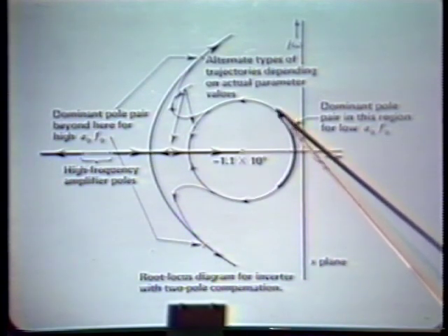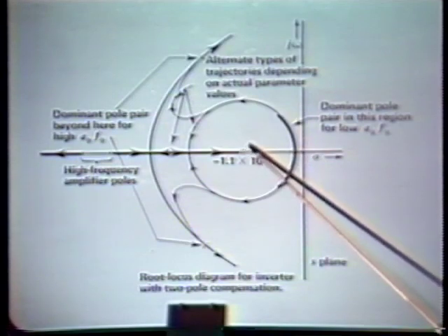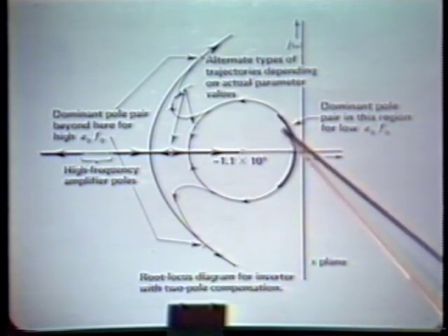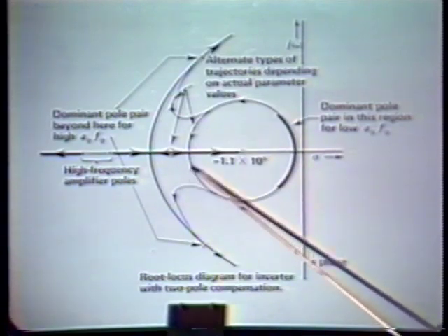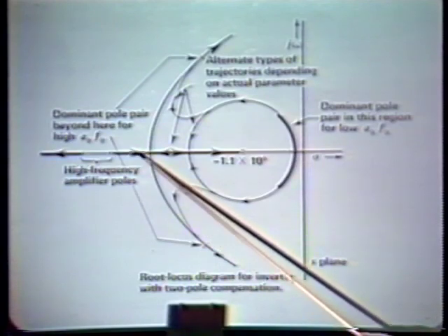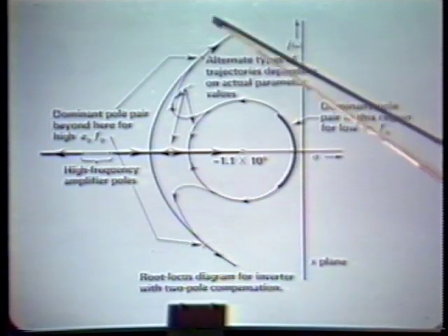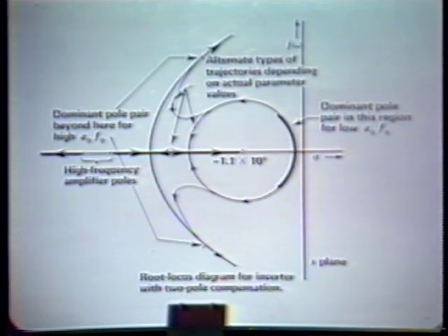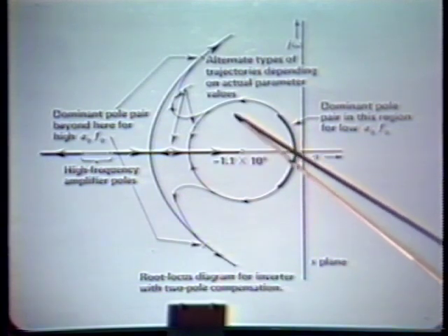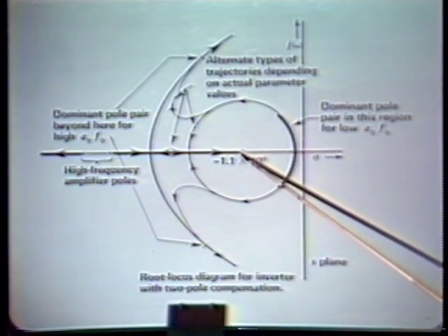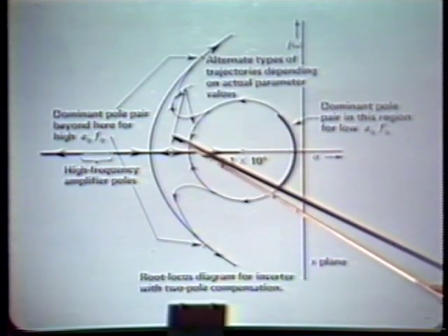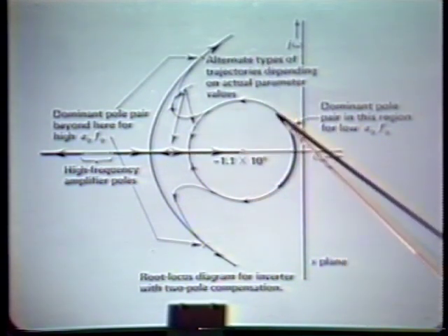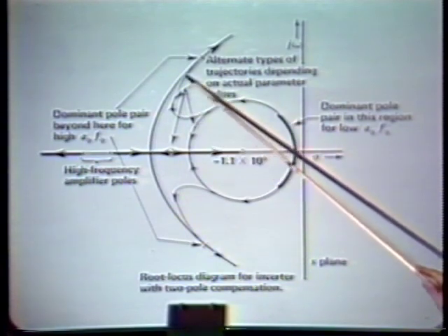We get a root locus picture that, depending on the relative spacing of the poles and 0, either circles around, comes back, one branch coming back to the 0, another one going out here, meeting an incoming branch, and then finally breaking off like so. Or, again, for a different arrangement of the 0 and poles, does something like this. We looked at this case in detail when we first introduced the idea of root locus.